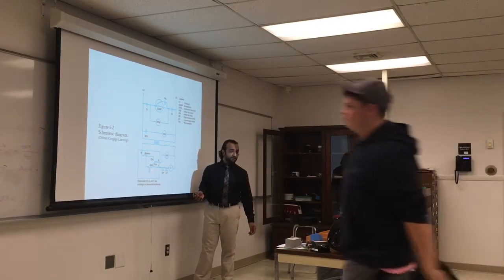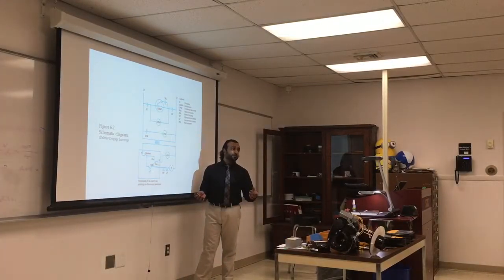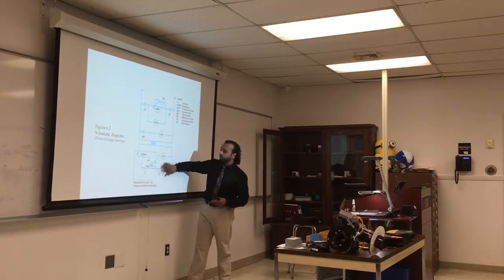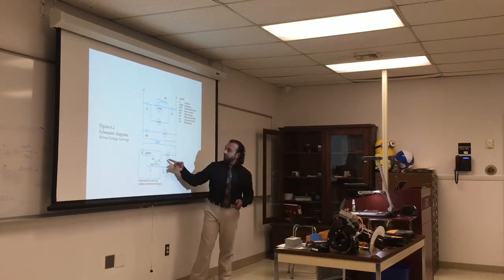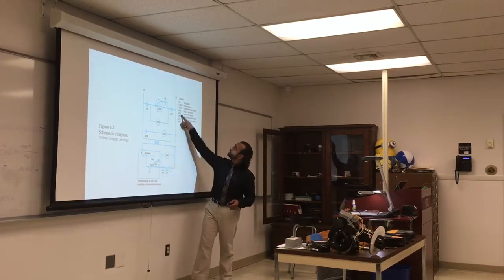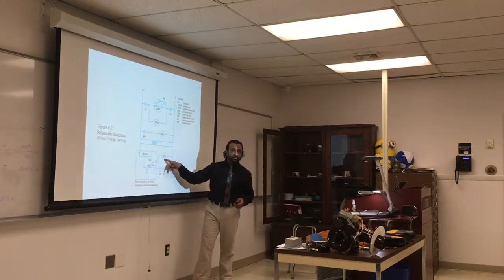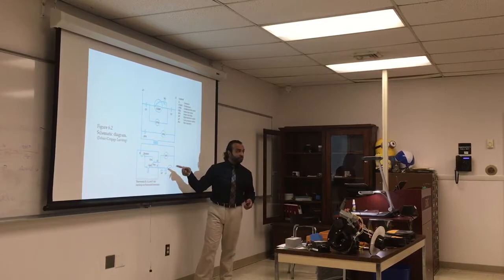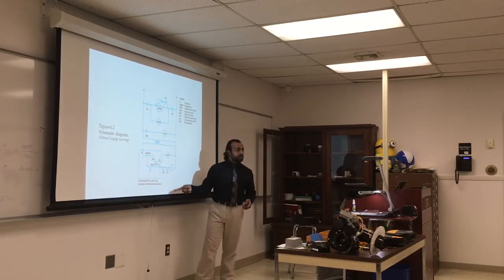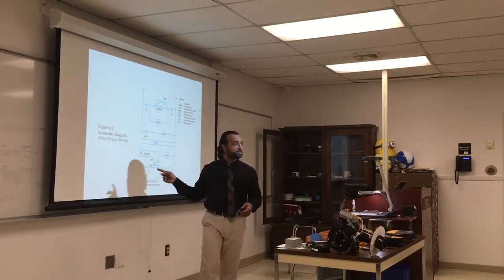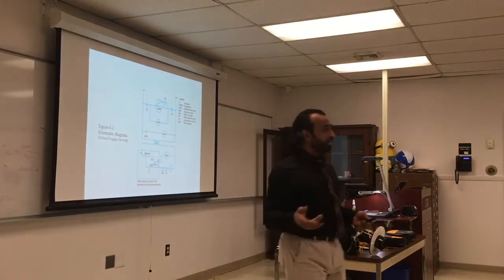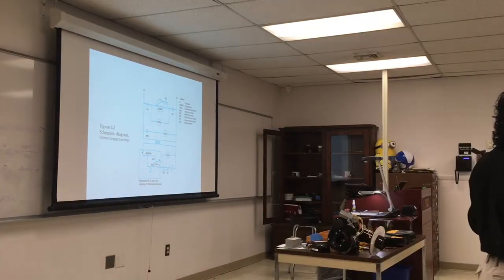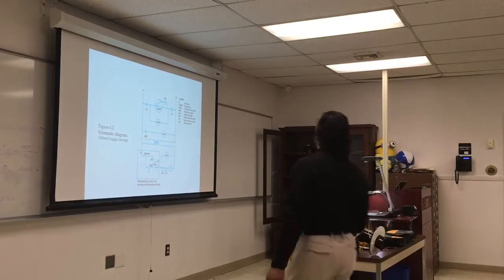Switch. Thermostat. What kind of thermostat? Cooling, because it's an AC. Okay, so this circuit here is the control. So this is a thermostat, indoor fan relay, turn on or off the fan, and high and low pressure switches for the system refrigerant. These are safety measures because if we exceed the pressure inside the line, it should shut off the system, otherwise you might have a problem with the compressor.